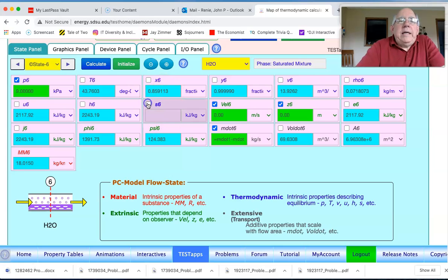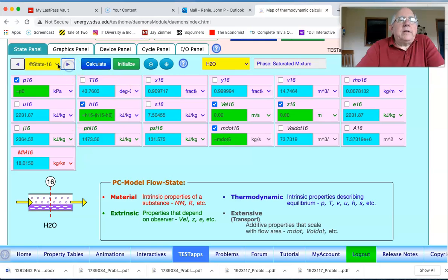And so we need to change this entropy to S15, okay, because it's actually starting at the state 15 and it's going through isentropically to 9 kPa. And so now we have the correct state for 15, and we have the correct state for 16. And again, because of the irreversibilities of the two turbines.